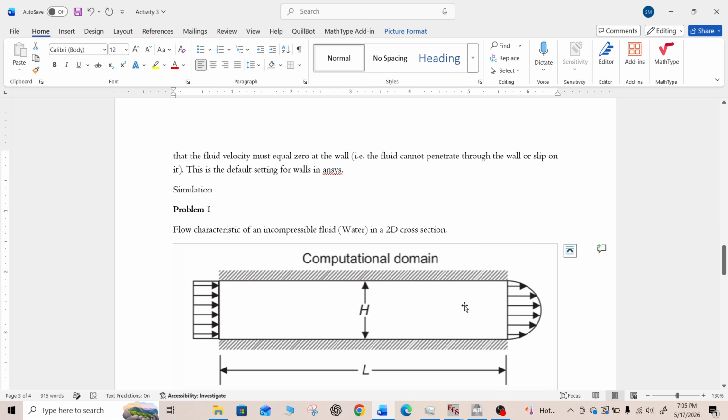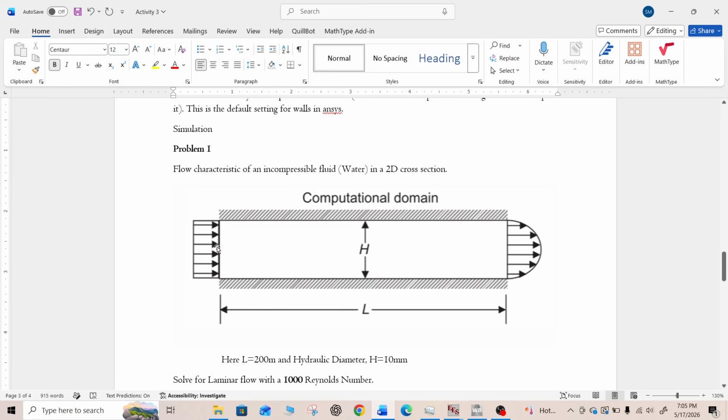Okay, it might be possible, but you have to make sure that when you set your boundary conditions, like in the inlet we have, let's say, a mass flow rate of 15 kg per second. So if you put the boundary conditions at the outlet, make sure that the conservation of the mass needs to be satisfied. That means throughout this whole region the mass flow rate does not change. So if it is 15 kg here, it should be 15 kg there.